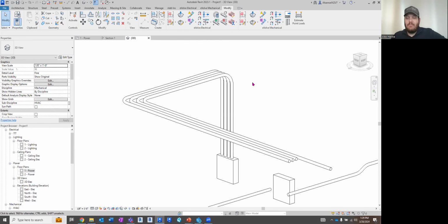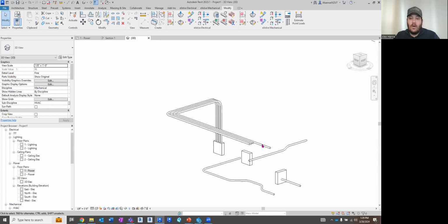So I haven't actually played with that, but if the conduit run goes from, hypothetically, 2-inch to 1-inch to a 1/2 inch, and they're all part of the same system, you can use parallel conduits in that. That's using that tab key.